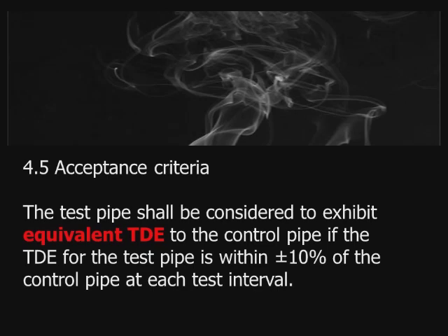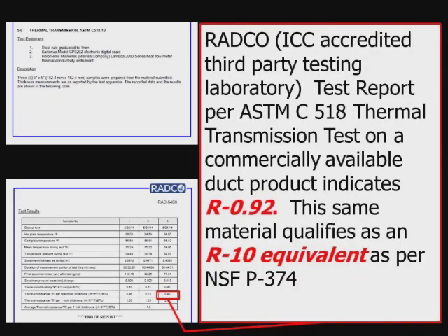So in discussions with NSF and through our own studies, we took a commercially available product, and we actually had it tested per ASTM C-518. And again, this is measuring how much heat can pass through this particular material. When this test was done by a third-party ICC accredited lab, called Radco out in Long Beach, California, it came back that this material had less than R1.